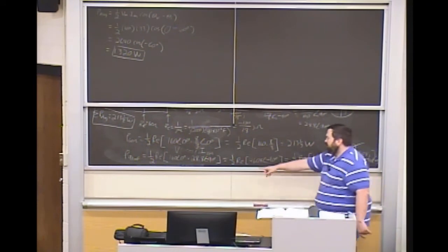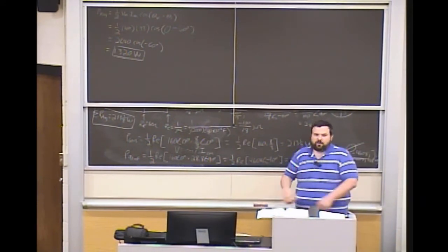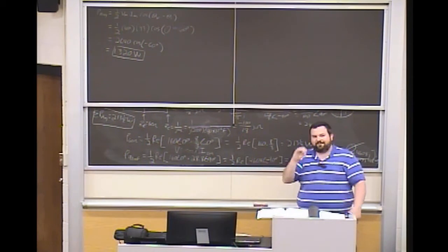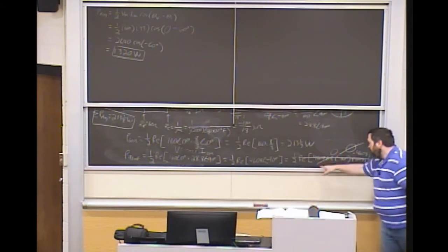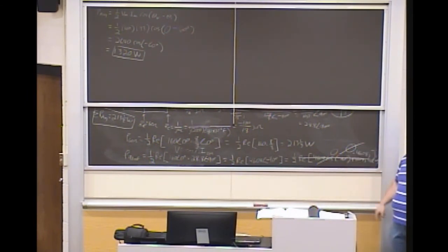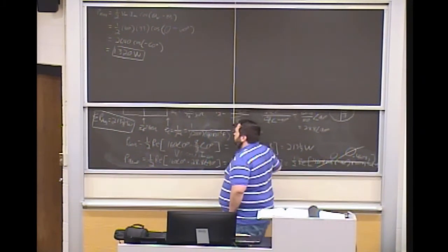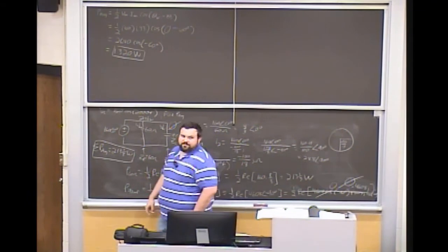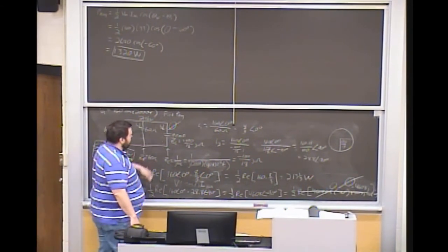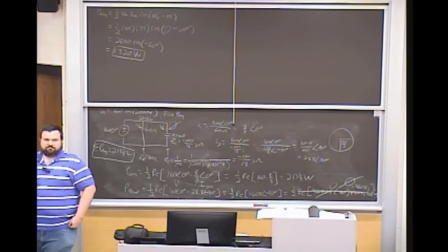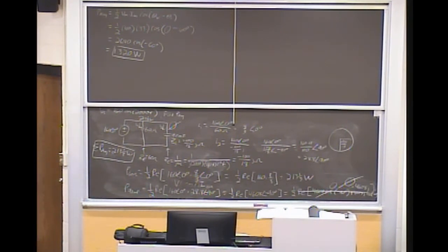But what I'm looking for is the real part of that. All I end up with is an imaginary component. I have 0 real component. And so this is my real component at 0. The entire real portion of everything in the bracket is just 0. All right? And that's because this was purely capacitive. It would be the same, but an opposite sign if it was purely inductive. If I had a purely inductive load over here, then my phase angle would just be the opposite sign, but it would still work out. The real component would still be 0.